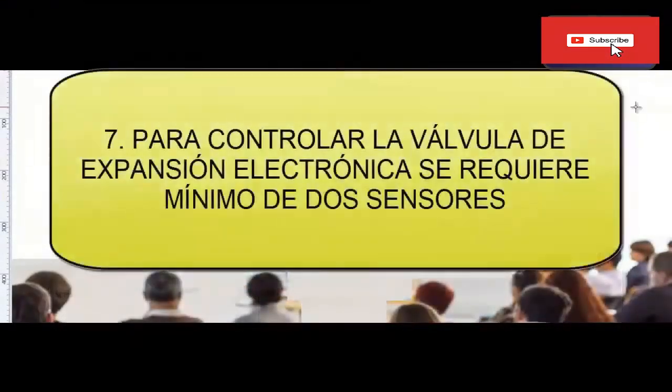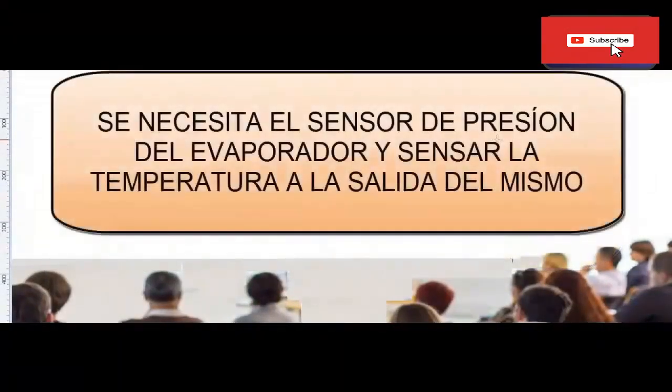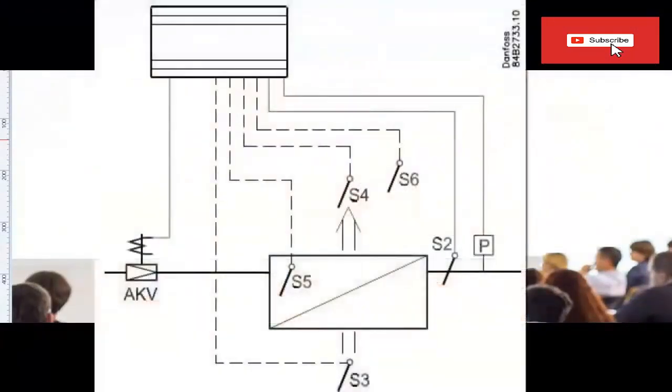7. Through the use of a pressure sensor and a temperature sensor, a correct measurement of superheat is achieved in any condition, which ensures a very precise and robust control. For example, superheat is measured by the pressure sensor, PE, and temperature sensor, STU. The temperature of the installation is registered through one or two temperature sensors, located in the airflow before the evaporator or after the evaporator, respectively.